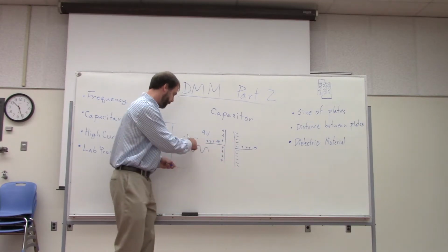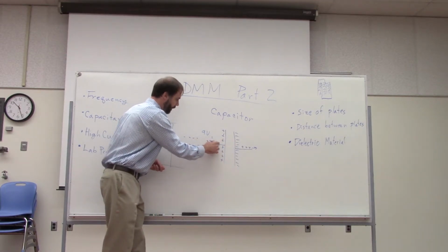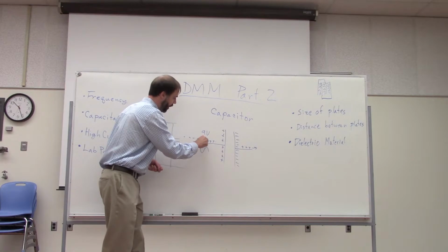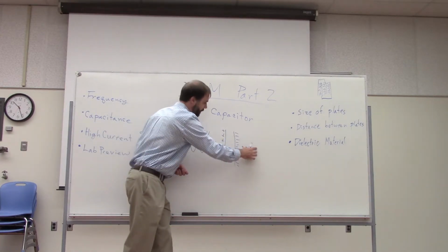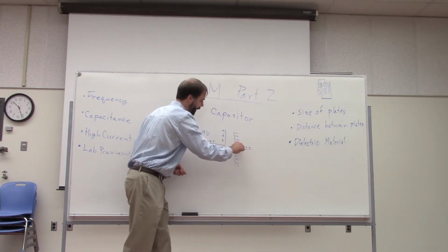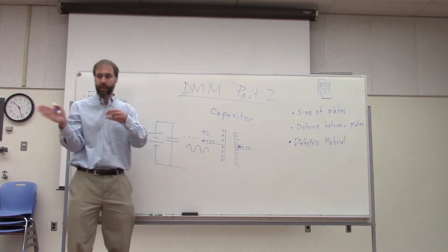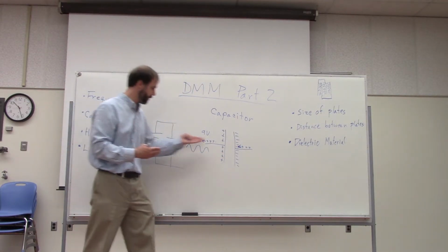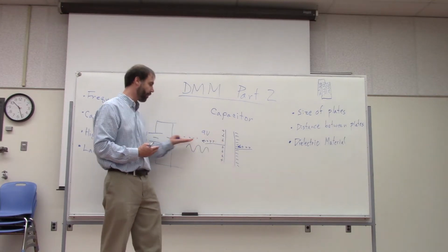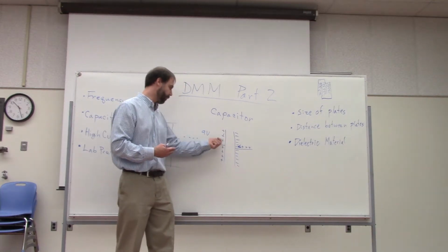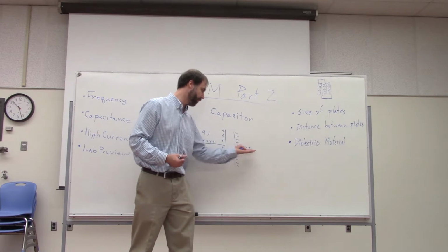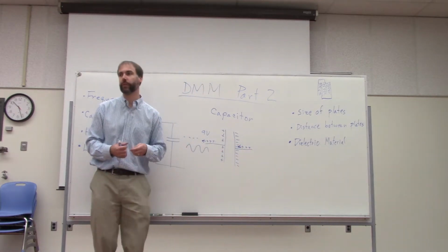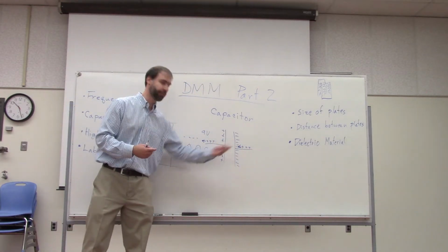And then the voltage goes down. So now that's pulling these charges off this side. So then that's pulling more charges back onto the other side. So you have this action where the charges are going on and off and on and off the one side, so that's causing them to go on and off the other side. So it seems like the electricity is going through.